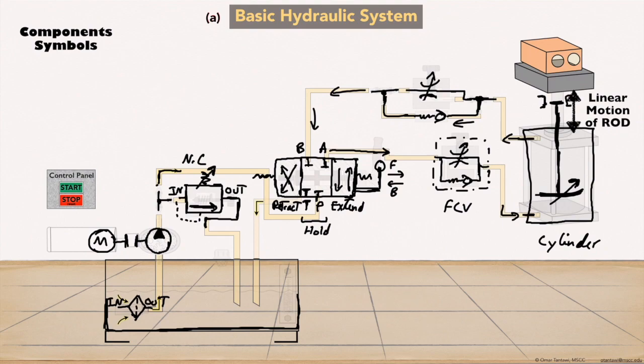When it goes back to tank, this is where I'm going to start adding the extra components. The first component I will add, which you'll see on most systems, is the flow rate gauge or the flow meter. It reads the flow rate. It looks like a baseball shape or a tennis ball shape. This is the in, and that's the out, and it cannot be switched.